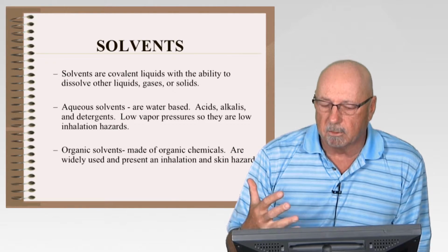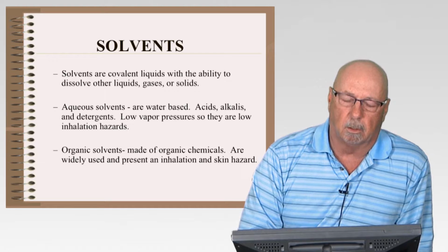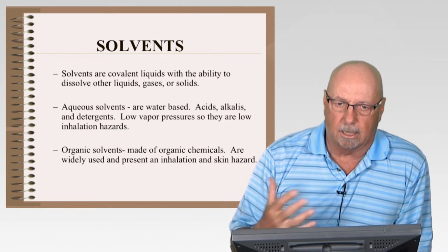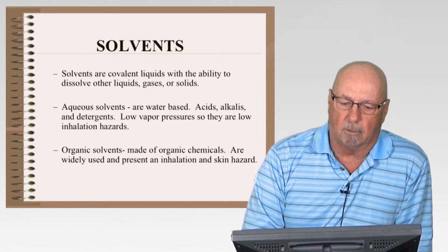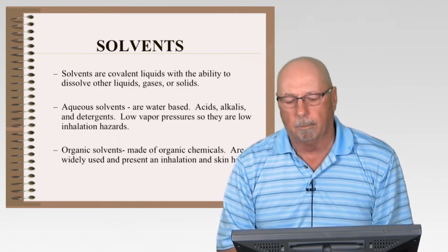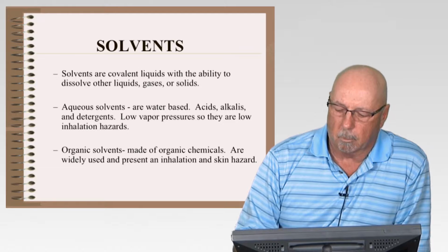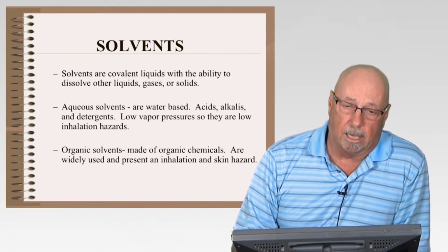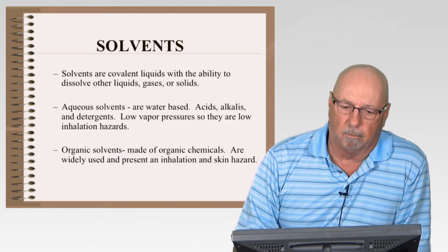So there's a trade-off. The aqueous solvents are perhaps more dangerous to us from a skin contact and eye contact standpoint, versus the organic solvents. But the organic solvents are more of an inhalation kind of problem, as well as, depending on the chemical makeup, can be more of a fire hazard to us as well.